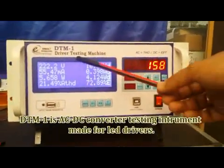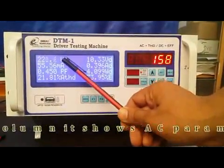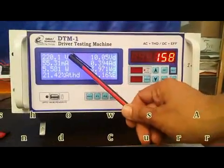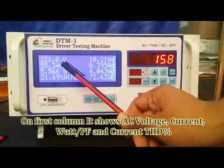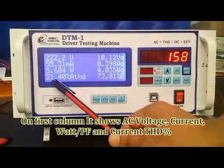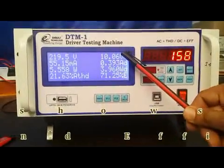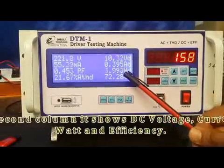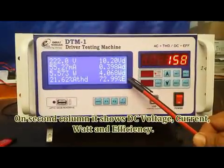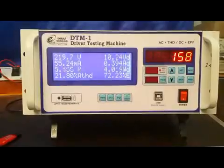This is a driver testing machine for testing of LED drivers. Now this is showing AC parameters here and DC parameters here. It is showing voltage, current, wattage and PF on the same display alternately, as well as the current THD. On the DC side, it is showing the voltage, current, wattage and the percent efficiency, which is the DC wattage divided by AC wattage into 100.